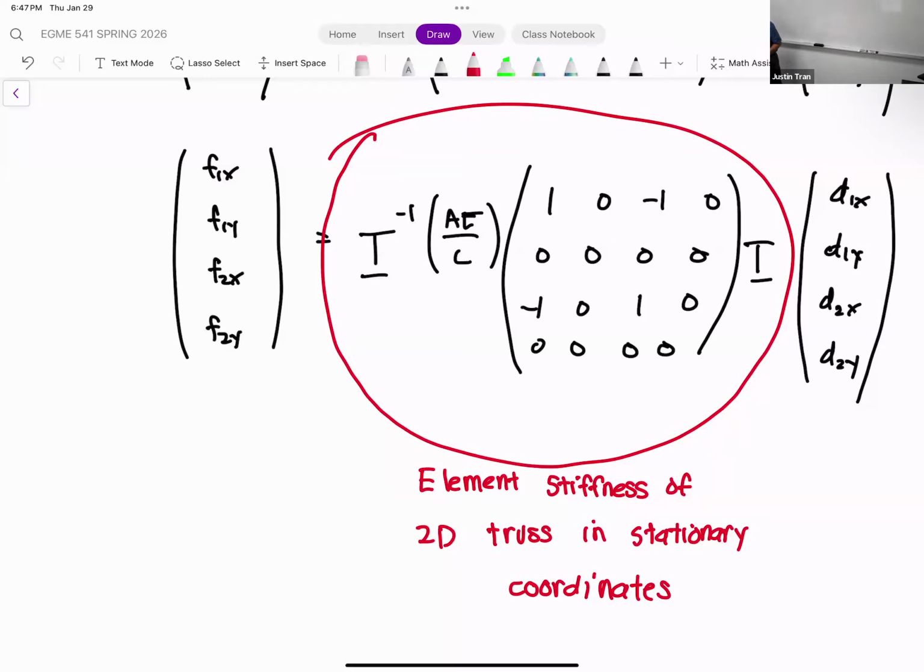Pretty much correctly, but the only thing is it doesn't look like you have the fixed support. I see the force here, but you need to apply the boundary condition, otherwise this system won't be solved.